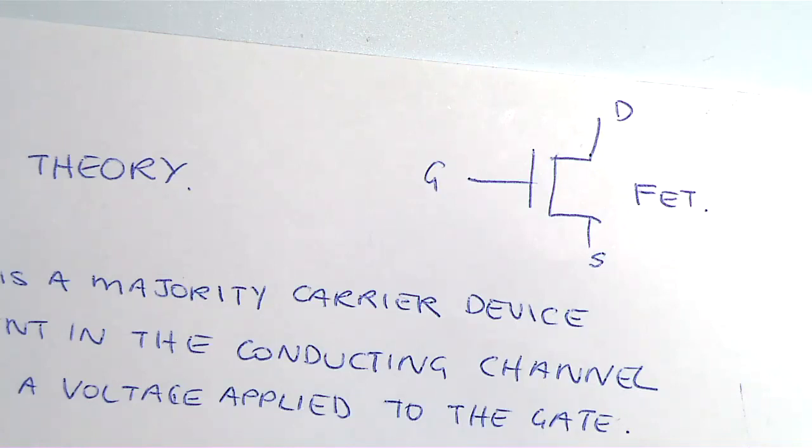But what I would suggest is, you can bring your materials, but write down on a piece of paper: how do I work out stability of a power amplifier? How do I determine, if I'm doing matching, what do I need to do? What's the input and output impedance? Input and output reflection coefficients in terms of the scattering parameters. How do I work out stability circles?